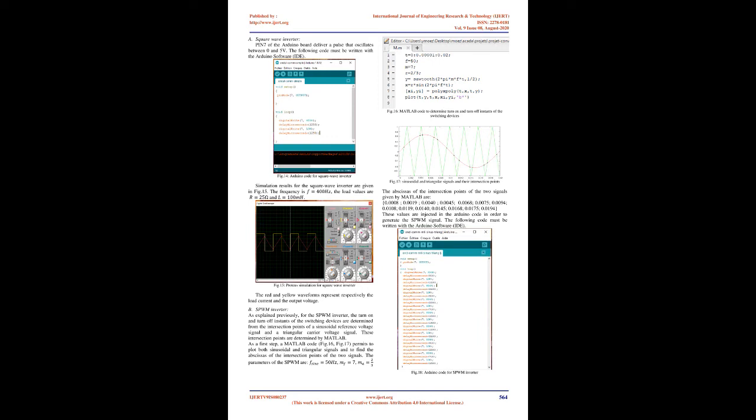Widely employed in basic programming projects, it contains a 16 MHz clock, 14 digital input/output pins, 6 analog inputs and 6 PWM outputs. It is based on the ATmega328P microcontroller and can be powered via USB connection or by an external power supply. The main advantages of Arduino are a simple and clear programming environment, inexpensive, open source and extensible software and hardware.